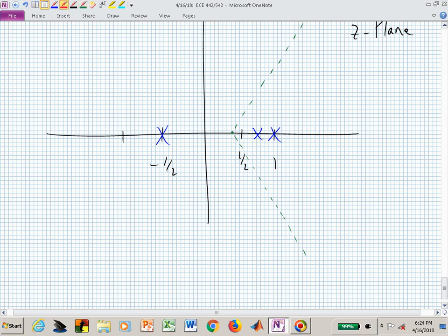But do you see that this segment belongs to the root locus, as does that one? This one's going off to 180. These two will break away. One will approach that asymptote. The other one will approach that asymptote. And that's a quick sketch of that root locus.